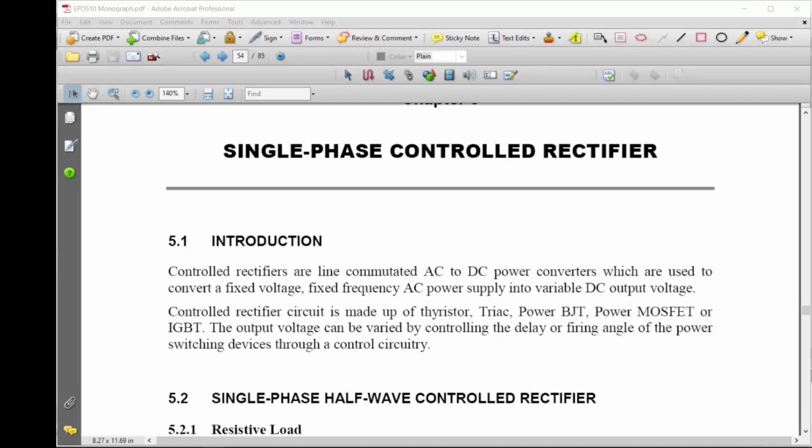So on Monday, we did look into the Fourier series, how you obtain the harmonic spectrum, the Fourier series equation, whereby you can identify the C1, C3, C5, all the Cn, isn't it? For the square waveform, right? So in simulation, we just use the FFT button, the fast Fourier transform, and PSIM will give you the harmonic spectrum, which tells you what are those sinusoidal waveforms behind the square waveform that we had, right? For the full wave rectifier with IDC.